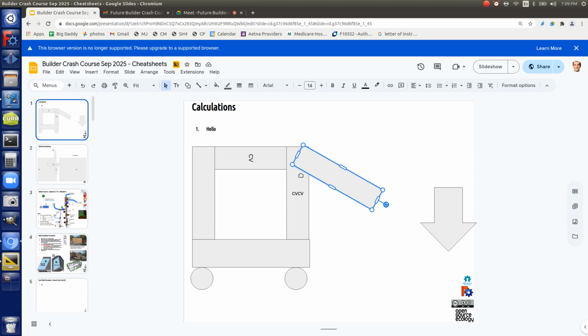Just from first principles. So 4x4 steel, it's hollow, it's 1/4 inch, so once again, PSI, pounds per square inch. You count up the amount of square inches you've got there for how much it can hold. So how many square inches is that? Each 4-inch wall, 1/4 times 4 inches, is 1 square inch. You've got 4 sides, so you've got 4 square inches. Is 4 square inches of steel going to hold 7,000 pounds?